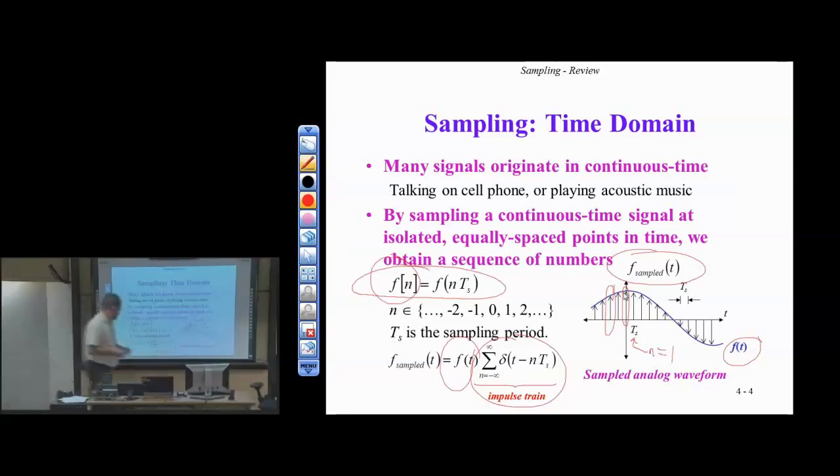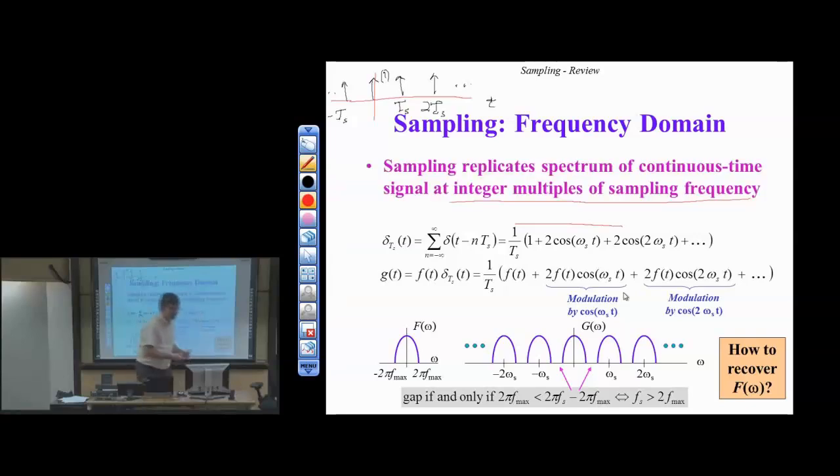When you sample, the effect in the Fourier domain is a convolution. Again, this is the time domain for the impulse train. The Fourier transform of this is another impulse train, scaled by the sampling rate; the area is scaled by 1 over Ts, or fs to be easier to write here. If we were multiplying in the Fourier domain, your observation would be right. We would only pick off 0, fs, 2 fs.